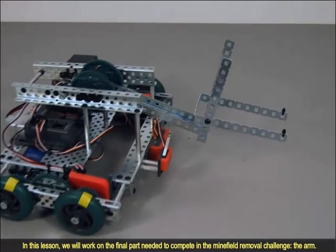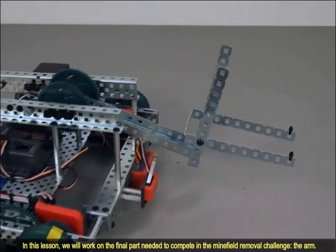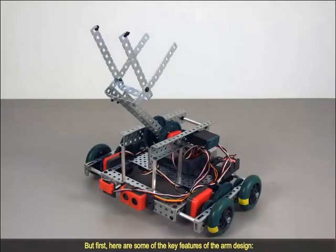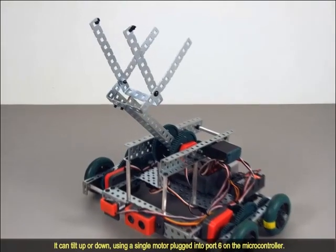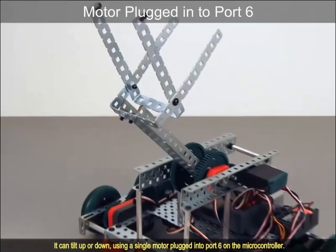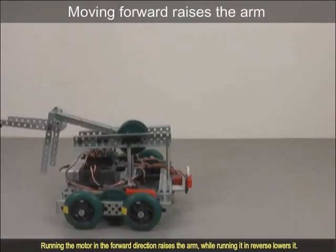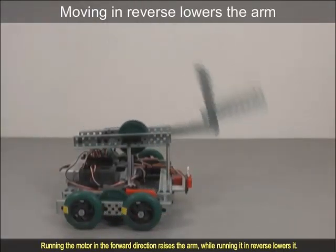In this lesson, we will work on the final part needed to compete in the minefield retrieval challenge, the arm. But first, here are some of the key features of the arm design. It can tilt up or down using a single motor plugged into port 6 on the microcontroller. Running the motor in the forward direction raises the arm, while running it in reverse lowers it.